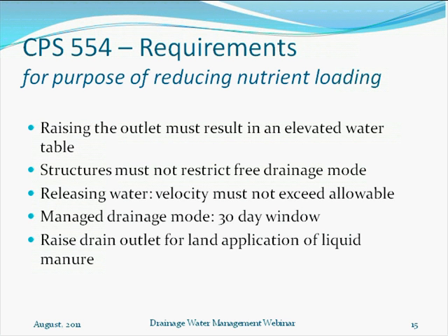Another requirement in the standard, remember I said about 10 days before planting, stuff like that? The standard allows up to a 30-day window. So before you plant in the spring, you could come 30 days in advance and drain your field. And in the fall, you could wait 30 days after your final field operation. But that's a requirement of the standard. It's always okay to do it in a shorter amount of time. And the final provision of the standard, as I mentioned before, is that you need to raise the drain outlet whenever you're going to be doing land application of liquid manure.